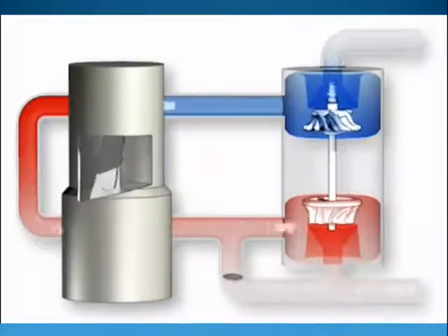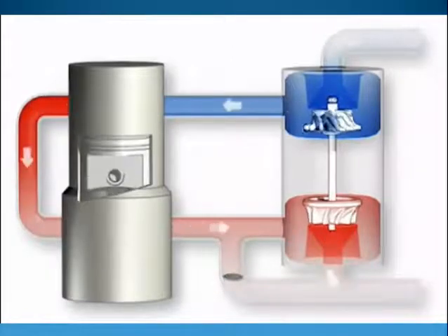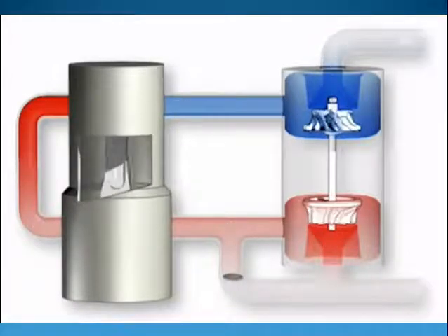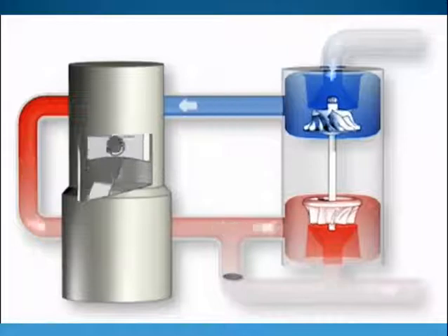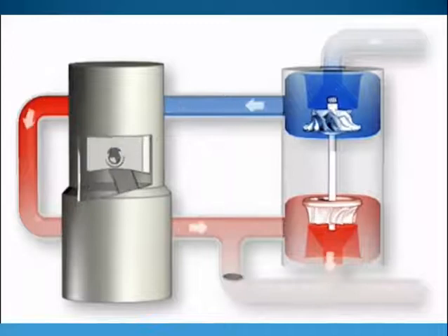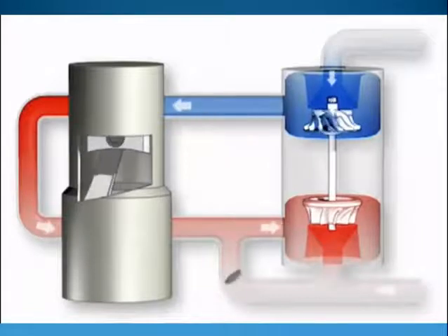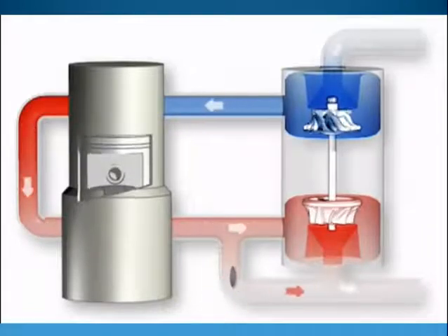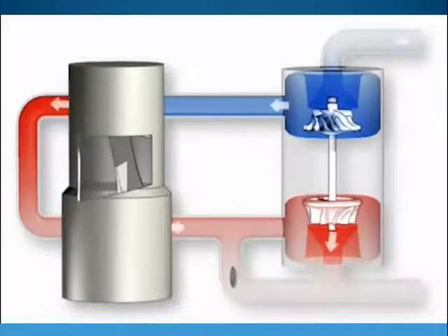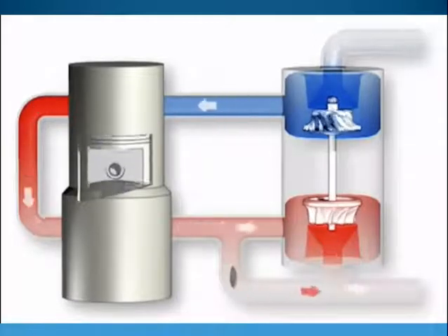The swing valve closes off the bypass between turbine inlet and outlet. Even with only a lower amount of available exhaust gas, the turbine achieves a higher speed of rotation which continues to rise with increasing exhaust gas quantity. When the turbine reaches the speed of rotation required for maximum charge pressure, the valve starts to open. This means that the turbine's speed of rotation remains the same, and that the exhaust gas quantity not required is bypassed around the turbine.